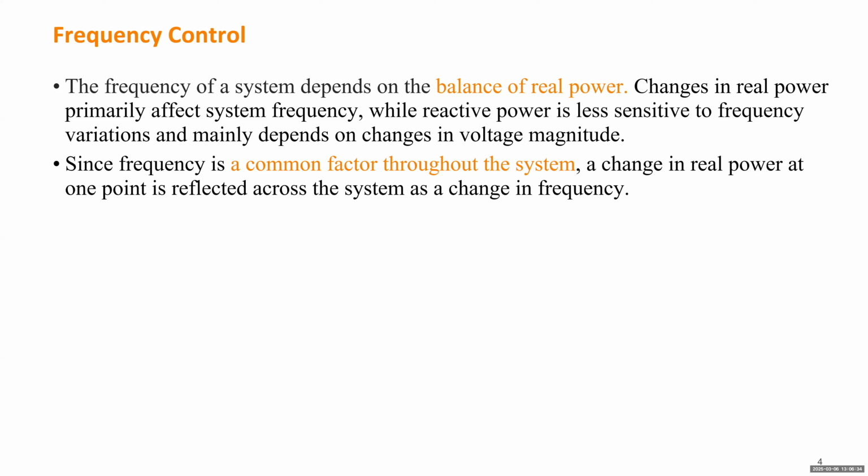That system frequency may be taken just from local data. That may not be close to the location of the fault, but eventually that value will reflect the system frequency. If your system is really huge, you can have multiple locations, but you really don't need a very accurate communication system because eventually your entire system shares the same frequency.